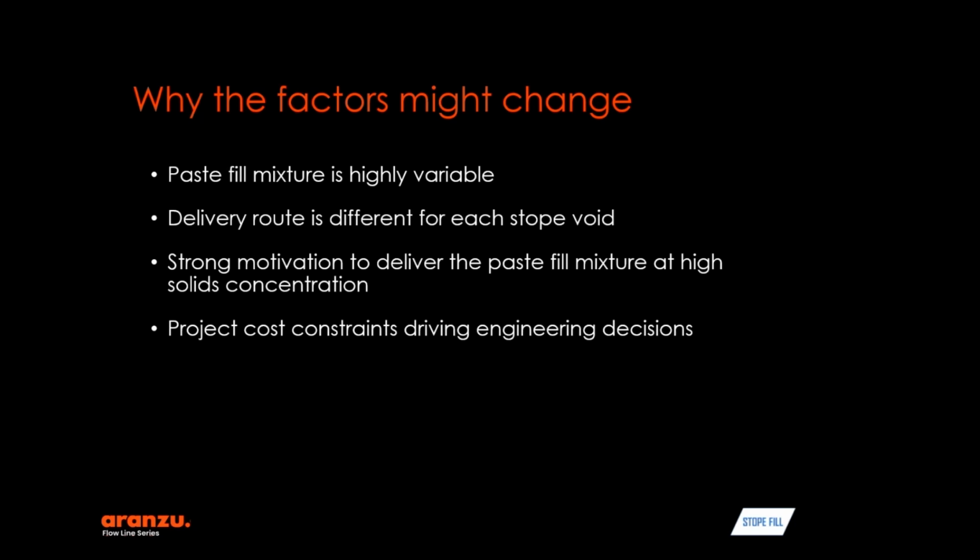The aforementioned factors may change due to the paste fill mixture being inherently variable. Aspects such as particle size distribution, mineralogy, particle shape, binder content. These factors will change the rheological parameters such as the yield shear stress, which has an exponential relationship with the solids concentration. This means that a good quality paste mixture is close to potentially causing a blockage event, and a good system runs close to the flow limit at high solids concentrations.